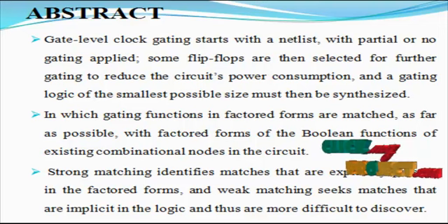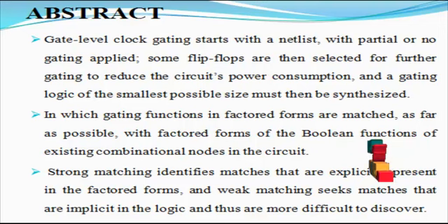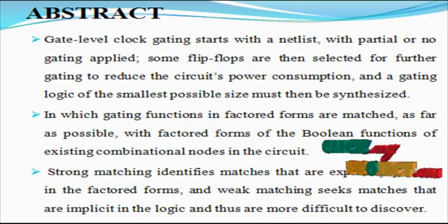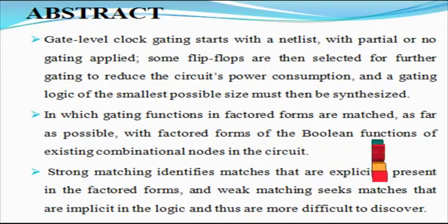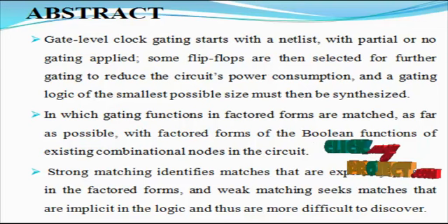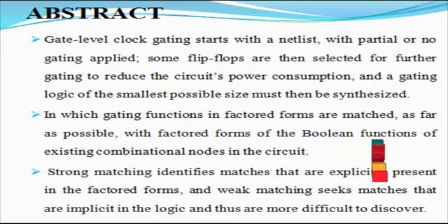Gate level clock gating starts with a netlist with partial or no gating applied. Some flip-flops are then selected for further gating to reduce the circuit power consumption, and the gating logic of the smallest possible size must be synthesized.